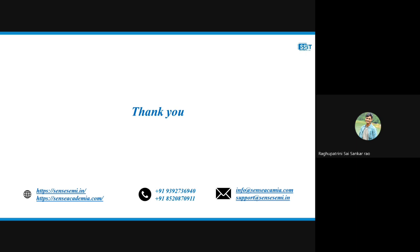But if there is a complex PCB where you need to connect jumpers or make traces on more than a single layer, then you have to go to the double layer. In some cases, the PCB size is the most constraining factor, as are the thermal requirements. Based on that, we will select either double layer or multi-layer. When we deal with a real-time example, you will get a very clear idea of that.